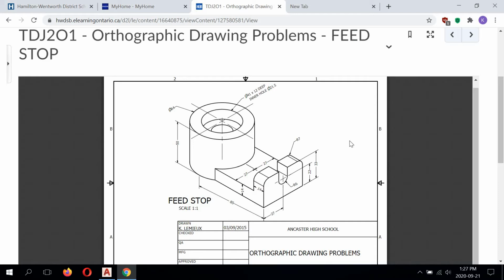This shows you what it looks like in a 3D view, but the proper term for this is called isometric view. So again, we're going to be creating the front view, which is looking at the part in this direction. The top view, which is up and down here with my cursor on top, bird's eye view, and we have right side view, obviously to the right of the front view. We're also going to learn how to use the circle command today under draw tools, which is something we haven't looked at yet.